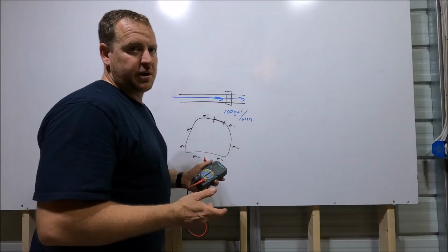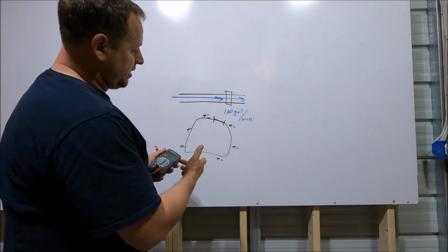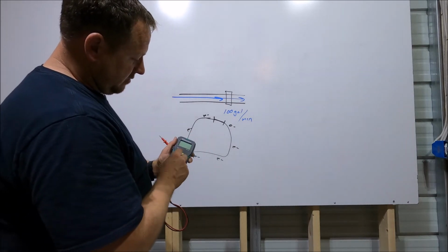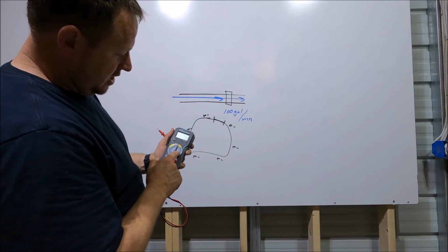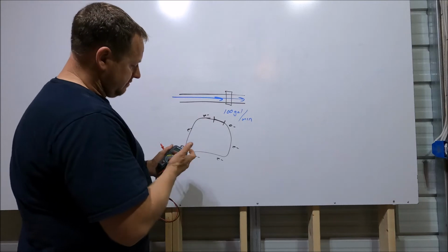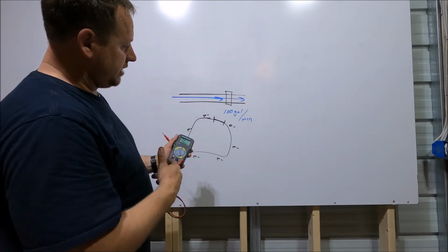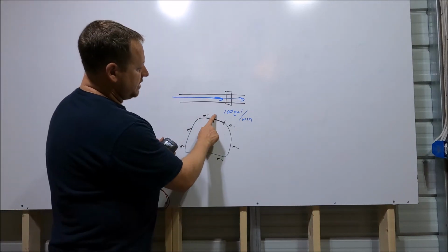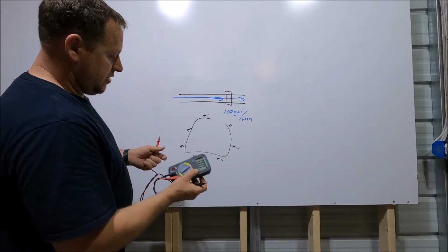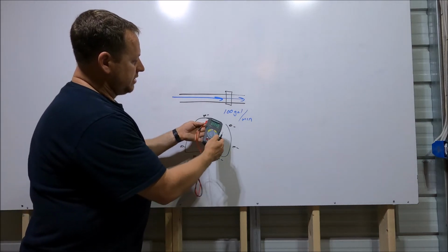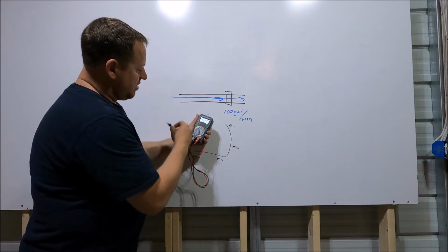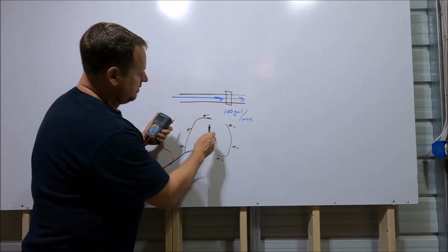But long story short, if you wanted to measure the amperage in a circuit, you'd have a setting on here where you need to know which type of amperage you have. So let's just say we're doing DC amperage. You'll turn it to your DC amperage setting. But then you have to actually break the circuit, and you have to hook the terminals up to each side of the circuit. Now the electrons are flowing through.